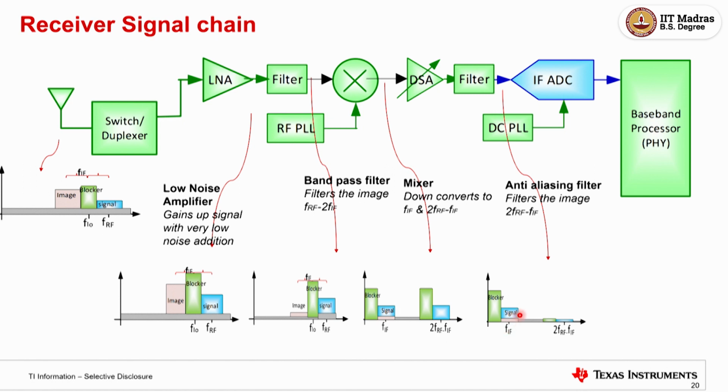Then this is the signal that goes into the ADC. As we saw, this is the bandwidth of the signal. The ADC just has to sample at double this frequency to make sure it is faithfully representing it. We saw the Nyquist sampling theorem. That's what it does, takes this in digital. It's just a copy. Now in digital, you can strip out this blue by a digital filter, because the blue and green are very close.